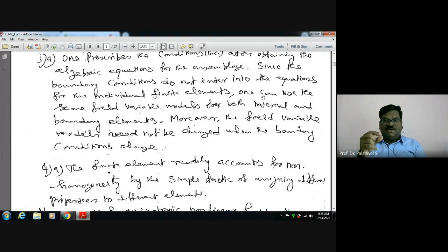The wrapping material I have modeled with some finite elements in the model. I have already assigned a material property, the glass fiber material property. If I change the material property to carbon fiber there, it becomes a carbon wrapped beam. That is all. Only such changes are possible. Hope you have got it. Very good. Next time we'll go to another discussion.